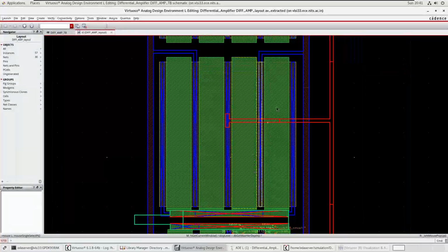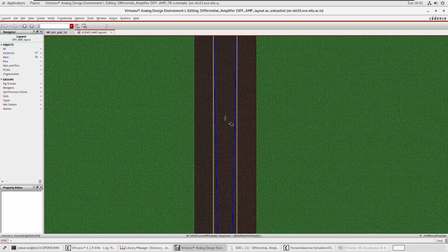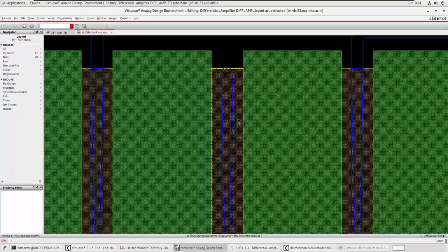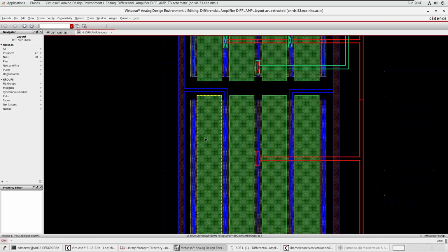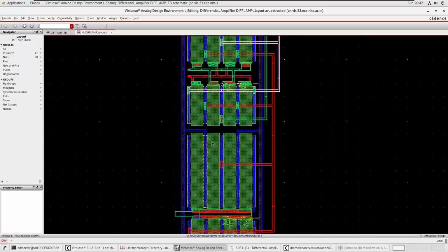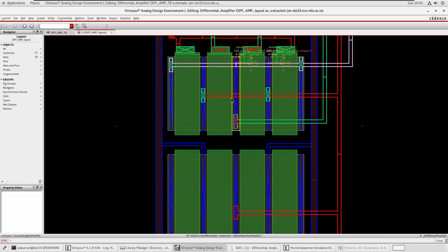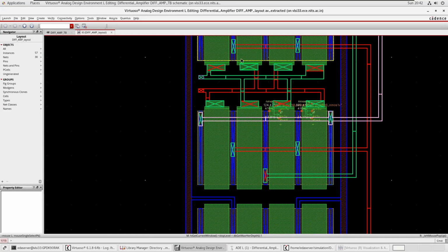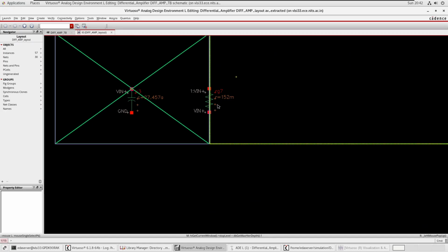If you check manually, you will find some capacitance. Here you can see some resistance is generated previously from ab extracted view. Using this view we have simulated. We have included parasitic capacitance and resistance in our simulation. So you can see resistance here, capacitance here generated.